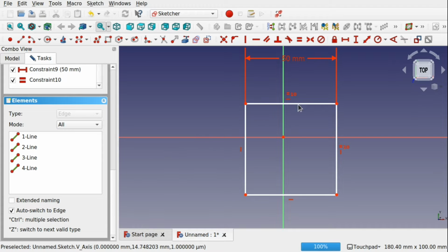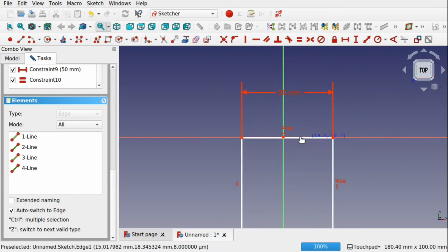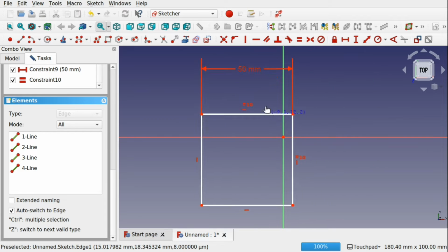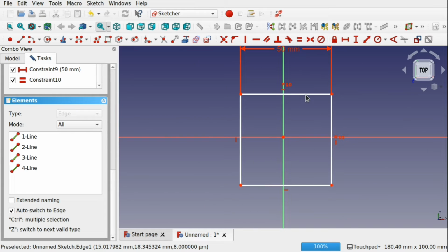But we're going to go back first to this now. So this is known as floating. It's not fully constrained. It's best practice to have it fully constrained, because going back to what we were saying before, if you have reference geometry to this one, if we start moving stuff about, then we can get breakages throughout that.